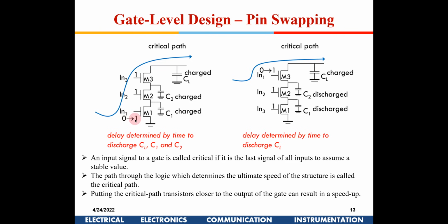So whenever this is going to 1, the output needs to be discharged to 0. And it will be discharged to 0 in this particular case when this is 1, this is 1 out here, right? When it is going to 1, now this charge which is stored here has to come like this to get discharged. This capacitance node also has to get discharged, because if you see, when it is 0 out here, this capacitance also gets charged to VDD.